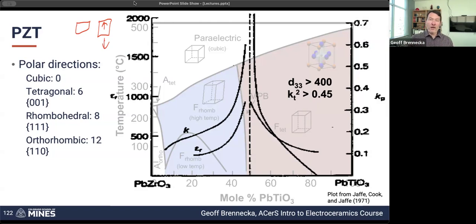And if you want to take advantage of that polarity by getting ferroelectric switching, or even in the other direction, when we talked about the direction dependent relative permittivity, you get much higher permittivity when it's along 100, right? Whichever direction you want, now you have 6 options for the tetragonal unit cell. In rhombohedral, because that polar direction is along the body diagonal, the 1, 1, 1 directions, now you have 8 possibilities.